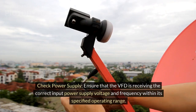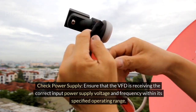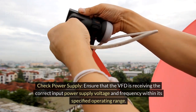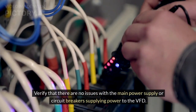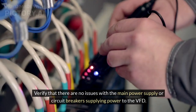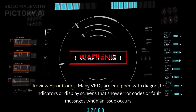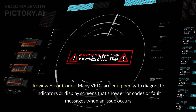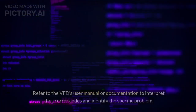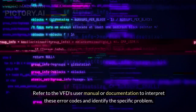Check power supply. Ensure that the VFD is receiving the correct input power supply voltage and frequency within its specified operating range. Verify that there are no issues with the main power supply or circuit breakers supplying power to the VFD. Review error codes. Many VFDs are equipped with diagnostic indicators or display screens that show error codes or fault messages when an issue occurs. Refer to the VFD's user manual or documentation to interpret these error codes and identify the specific problem.